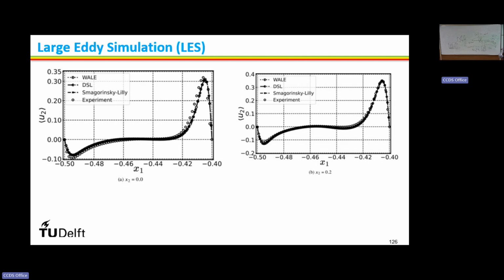They are very much accurate, just like we use for DNS. They are explicitly taking care of the LES; they call it implicit LES. But again, designing those numerical schemes in a commercial solver or open source solver is a very challenging task.